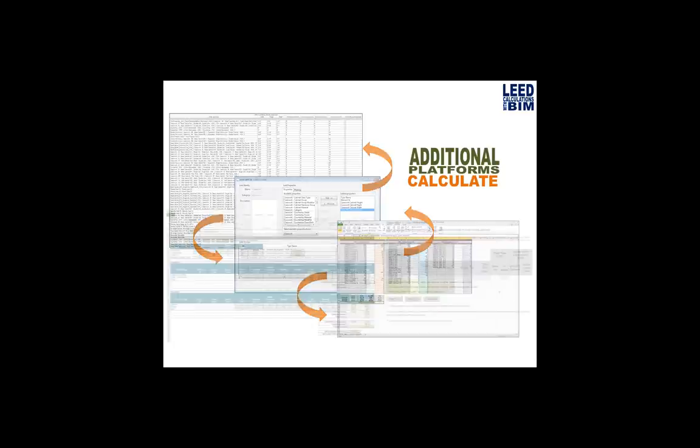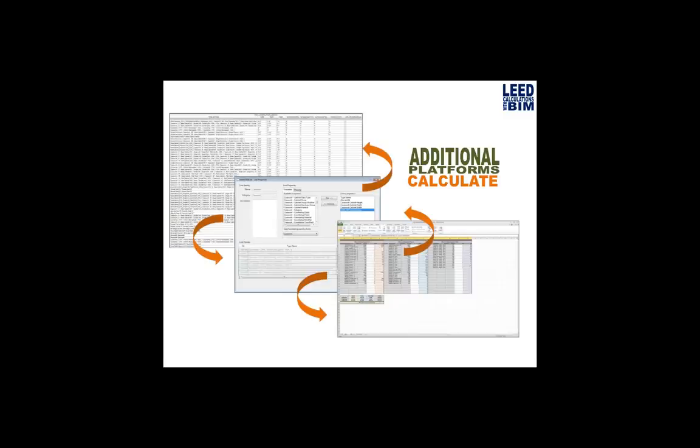Yeah. Have you also tried the access link, the Revit access or database access link? No. The DB link. I know that HOK uses a different version of the database management program. Right. But essentially all of these schedules and every other possible item that can be scheduled is actually built as an access database when you hit the RDB button. So in a lot of ways, you could actually, potentially manage the same information there. I was just curious if you tried that or not. No. I have not personally.